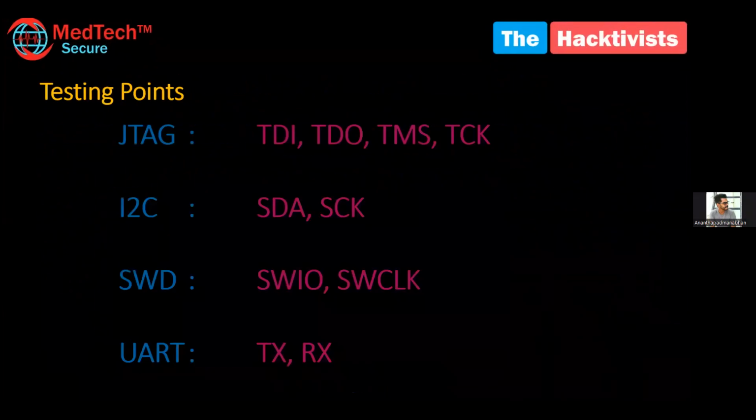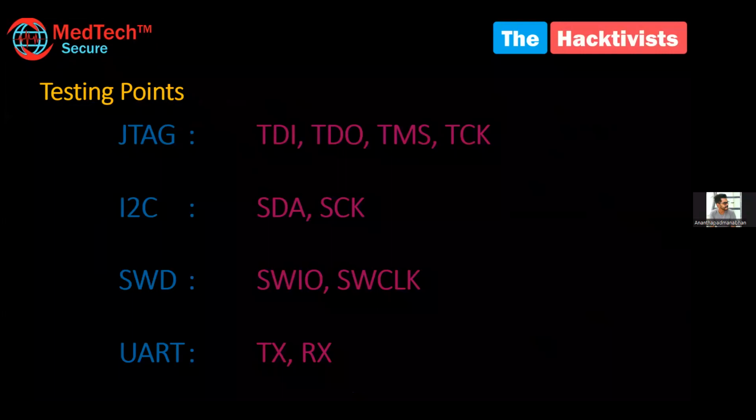Yeah, so here in the testing point part, we already discussed, suppose it is using a JTAG protocol, what all pins we have to look into. Now we have seen in that data sheet various kinds of pinouts. So suppose you have found TDI, TDO, TMS pins. What does that mean? That means that particular device is using JTAG. And suppose it doesn't have any TDI, TDO ports, but instead you have found SDA or SCK. That means it is using the I2C protocol in that particular device.